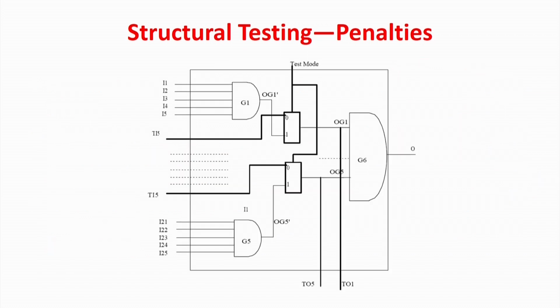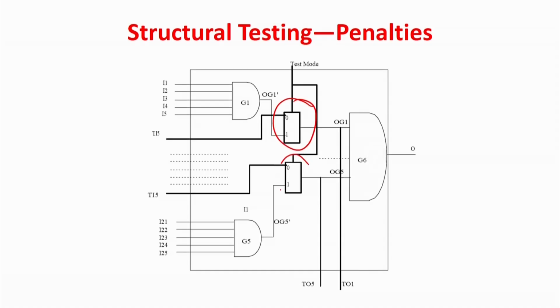This is a picture of how to do that, even if you have a pinout. You can see they have put in a multiplexing arrangement and these are the pinouts they have brought out. I am just going to give you the gist, because you can easily find it in any textbook. This is a multiplexer. Whenever you want to apply something directly to this gate, you cut this out to the multiplexer and give the input directly from outside.